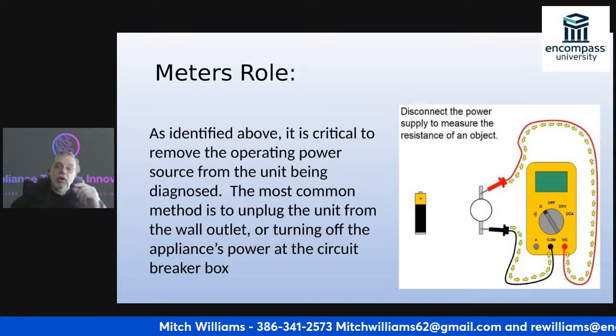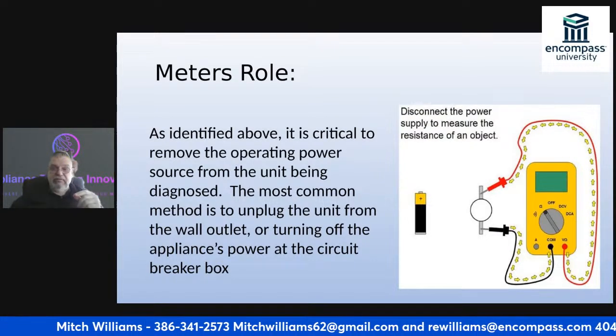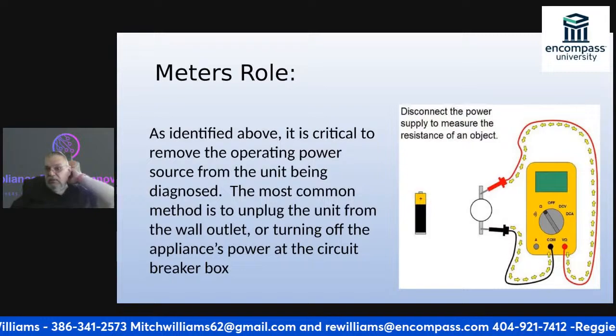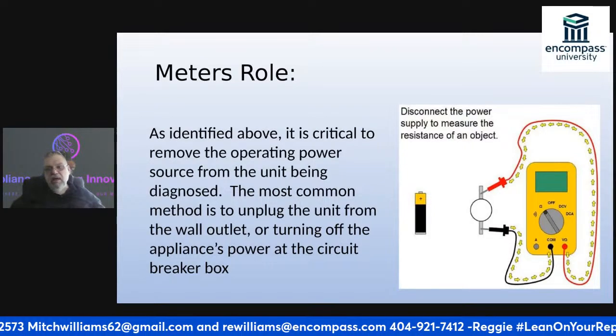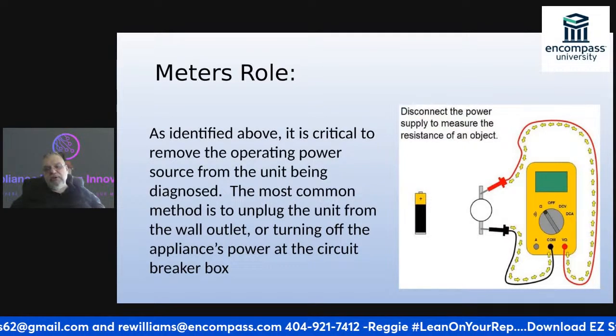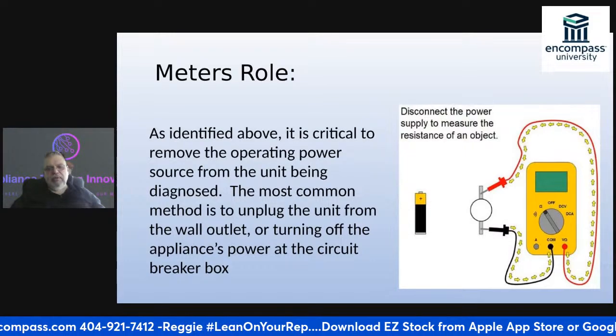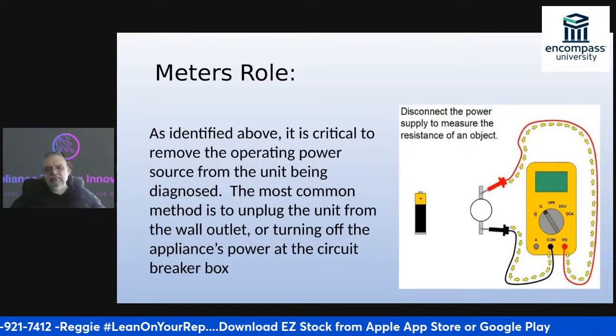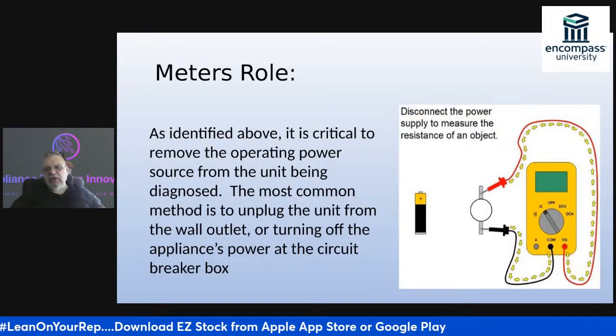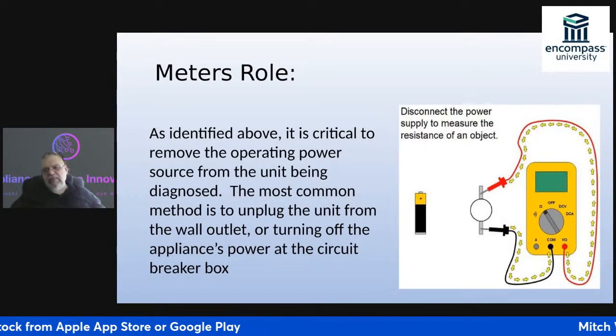We want to make sure that everybody's safe. As you see, this one right here has a battery. It does not have a fuse. You'll blow this meter up if you have it plugged in. If you look at this, it shows the path for the common. It flows through the meter and goes out to the other side.